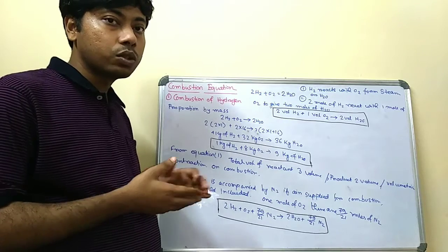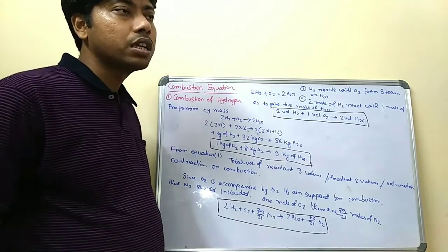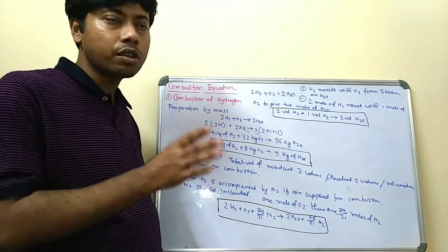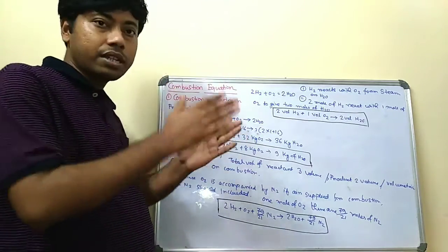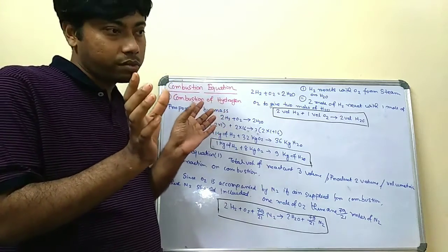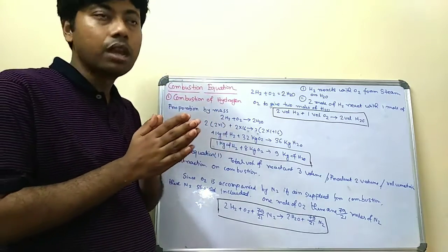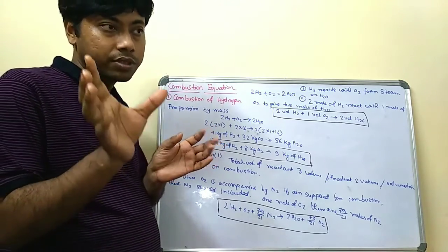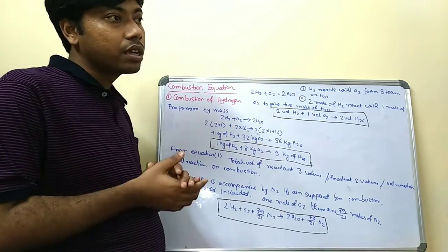In a combustion equation, or any chemical reaction, there are reactants and products, on the left and right sides of the equation. Applying conservation of mass, the total mass of reactants should be equal to the total mass of products. After the reaction, the total mass of products should equal the total mass of reactants at a particular pressure, temperature and composition.